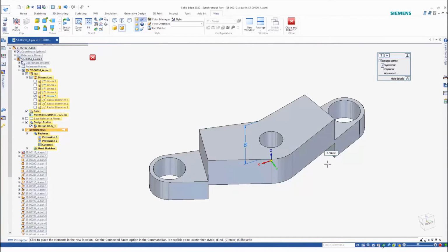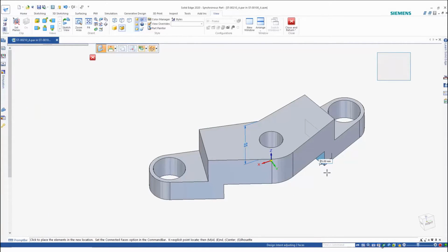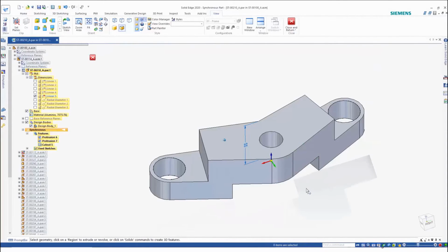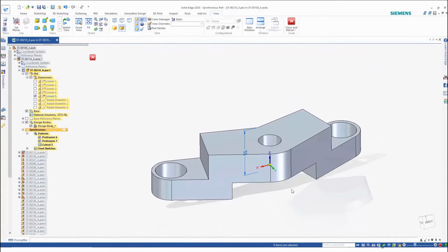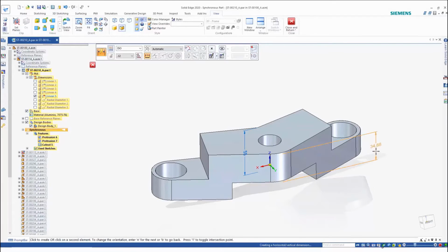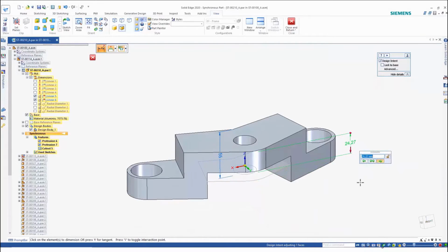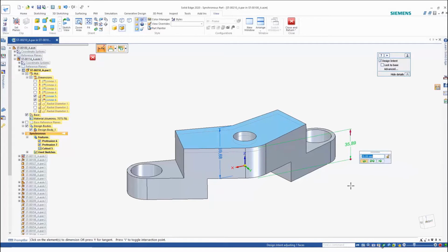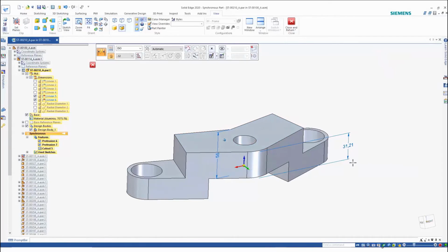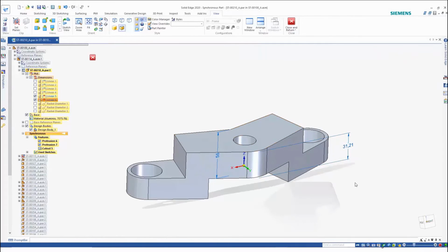Most 3D CAD systems require you to carefully plan the design steps so that edits can be made later. Using synchronous technology, we can create geometry in the most convenient manner, but have total flexibility in altering the intent later. 3D driving dimensions can be added at any time to simply edit or lock a design feature into shape. Again, notice the PMI drives the model and gives the designer the flexibility to specify exactly how the change will be made, something sketch dimensions don't allow for.